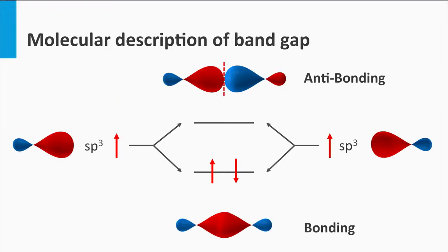In week 2 we discussed that 2 individual sp3 hybrid orbitals of a silicon atom can make an anti-bonding and a bonding state. The same is valid for the 2 pz orbitals, making a molecular pi orbital. They make a bonding and anti-bonding pi state. Therefore, conjugated molecules can have similar properties as semiconductor materials. Most electrons are at room temperature in the bonding state, also referred to as the highest occupied molecular orbital, HOMO. The anti-bonding states can be considered as the lowest unoccupied molecular orbital, the LUMO.